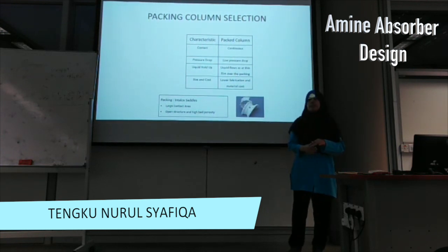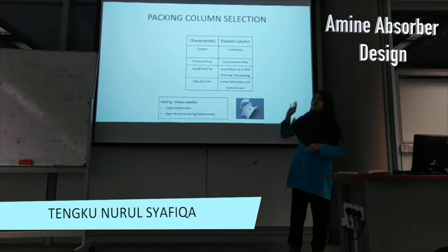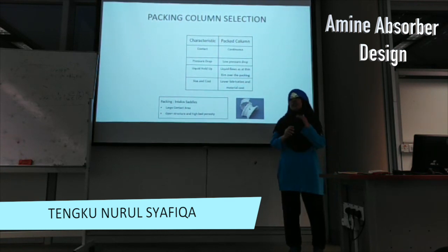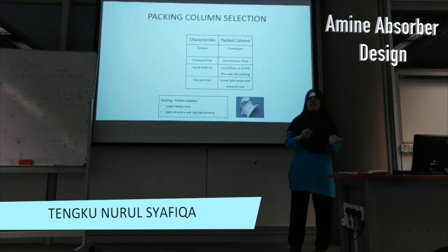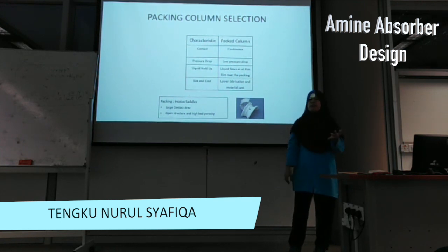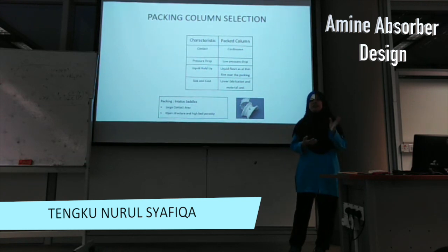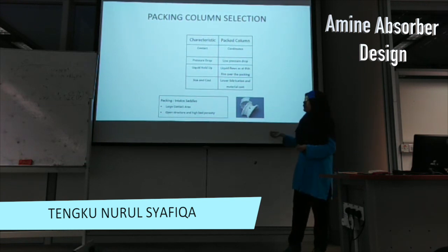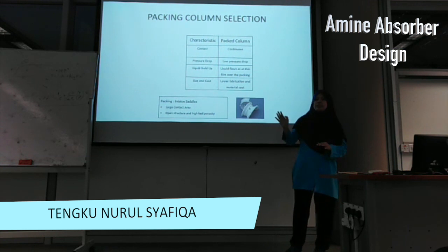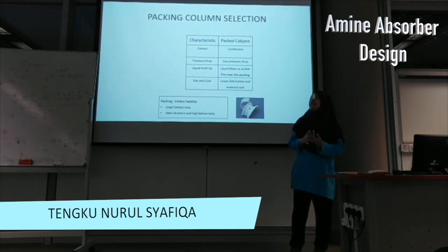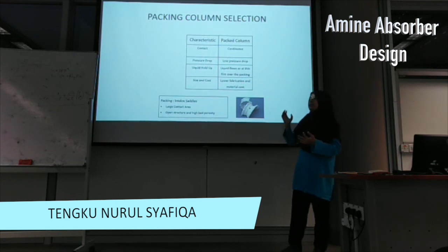Other than that, packed columns have many materials that we can choose to construct them, so in other words, we have more choice of materials to construct the column. Last but not least, foaming liquid can be handled more readily in a packed column compared to others.